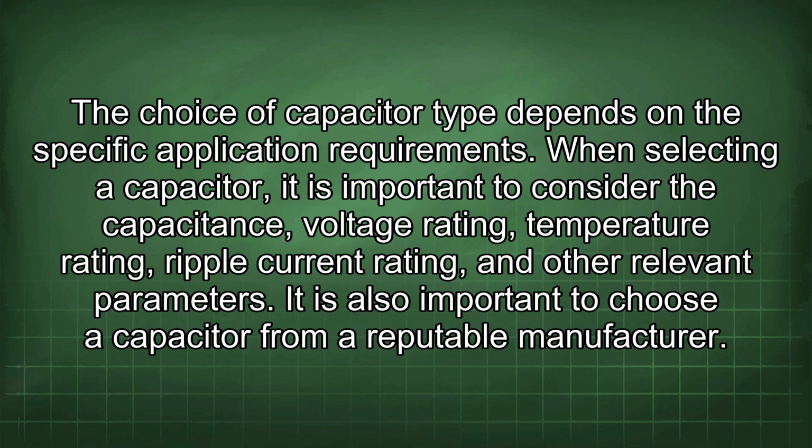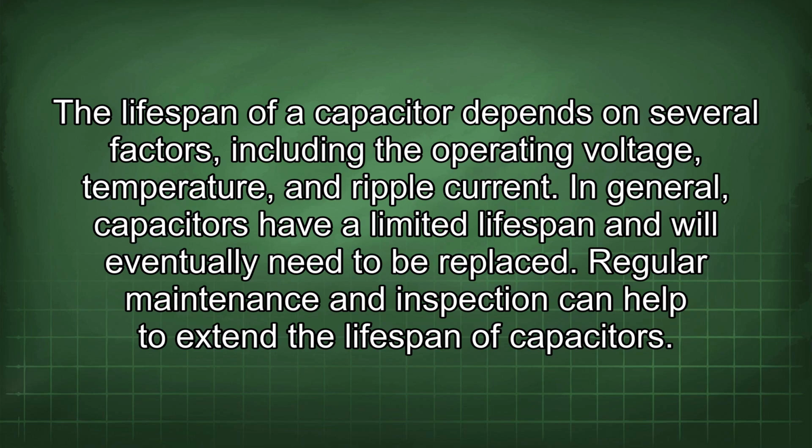When selecting a capacitor, it is important to consider the capacitance, voltage rating, temperature rating, ripple current rating, and other relevant parameters. It is also important to choose a capacitor from a reputable manufacturer. The lifespan of a capacitor depends on several factors, including the operating voltage, temperature, and ripple current. In general, capacitors have a limited lifespan and will eventually need to be replaced. Regular maintenance and inspection can help to extend the lifespan of capacitors.